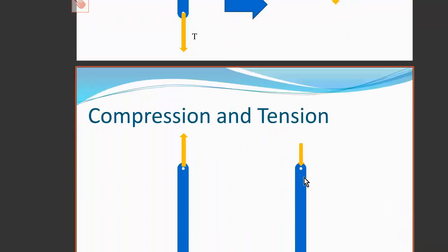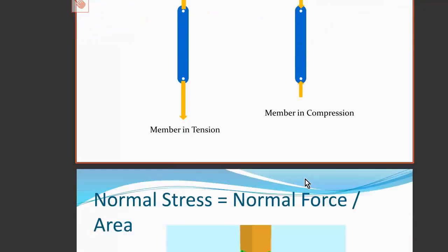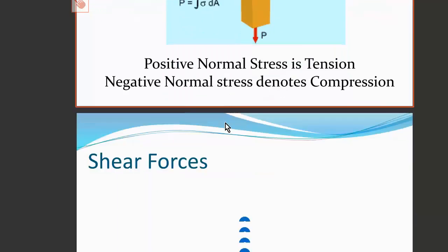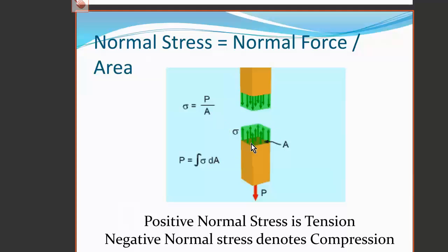This internal force acts over an area, and the internal force may be either tensile in nature, which means it is stretching, or compressive. Let's have a look at the internal force. In this case, we see an internal force that is acting perpendicular to the cut cross-sectional area of the member. We know that the addition of all the forces acting on the top area here must equal the force being applied. And that's what this integral says.